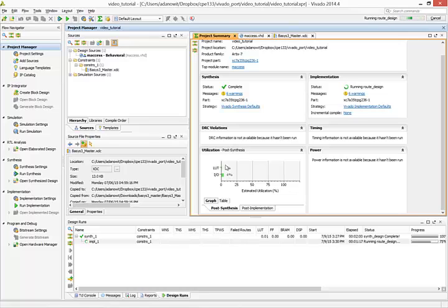Now, as you can guess from something like this, one of our big constraints on FPGA is our input-output constraints. But that's true on a lot of chip designs. We can put millions of gates on this FPGA, but we only have something like, say, 50, 60 pins that we can use to talk to the outside world.